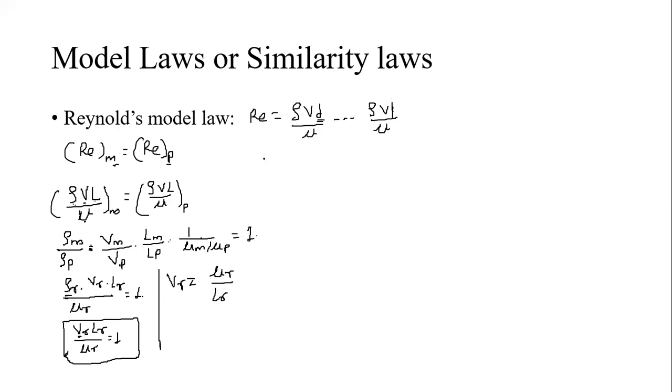Then from the Reynolds law, we will be able to predict the different scale ratios, that is for time, velocity, already we had acceleration and discharge. So the time scale ratio will be once again Tr equals Lr divided by Vr. How come? Velocity equals length upon time, length per unit time. So Tr will equal Lr by Vr.